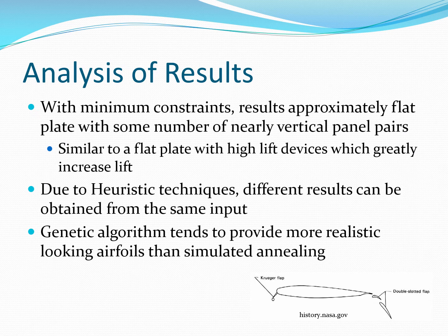With minimum constraint usage, fairly realistic representations of airfoils with high lift devices, such as flaps, were obtained. Due to the heuristic techniques used, different results were obtained from the same inputs, and overall, GA seemed to provide more realistic results than simulated annealing.